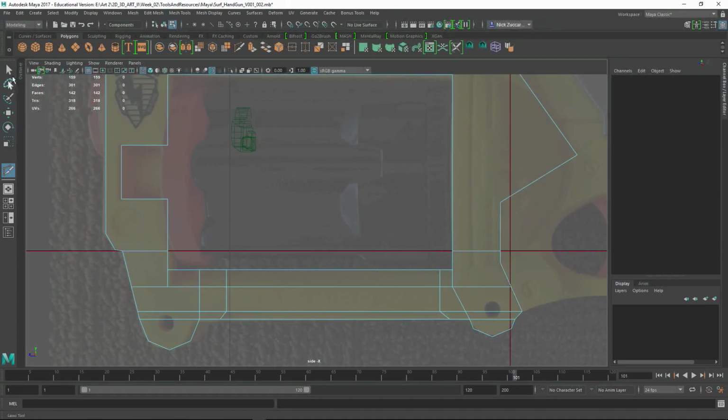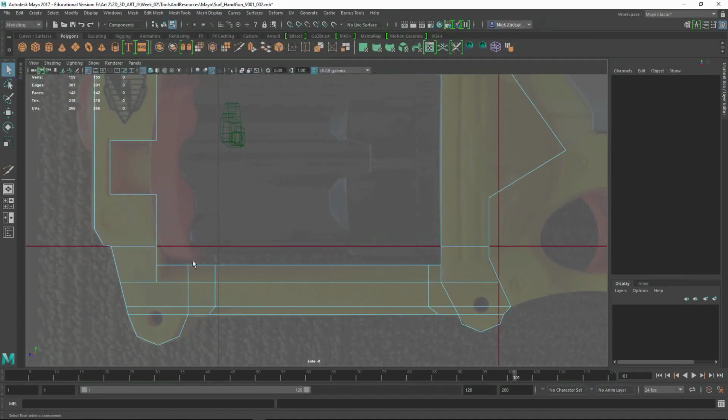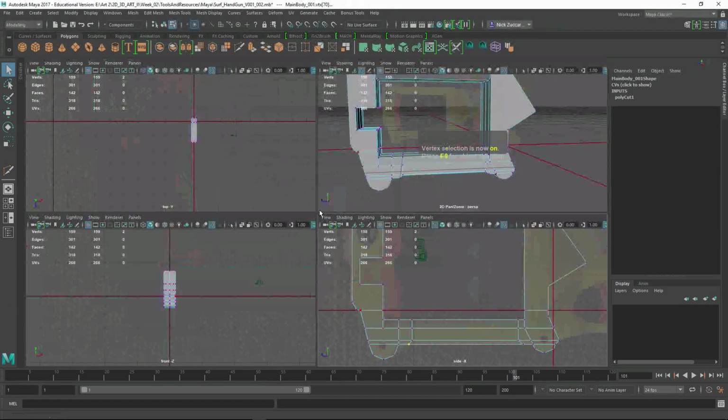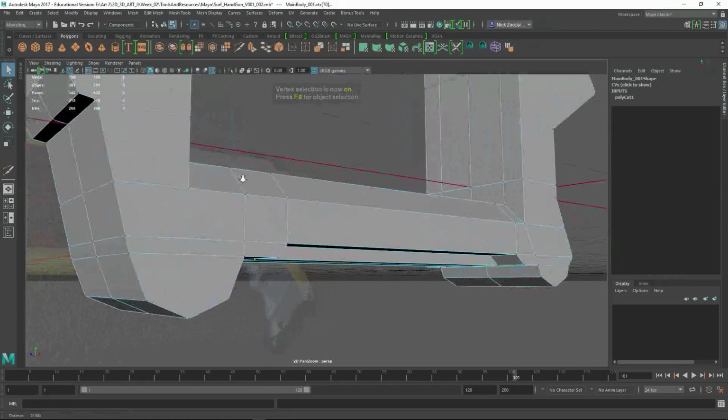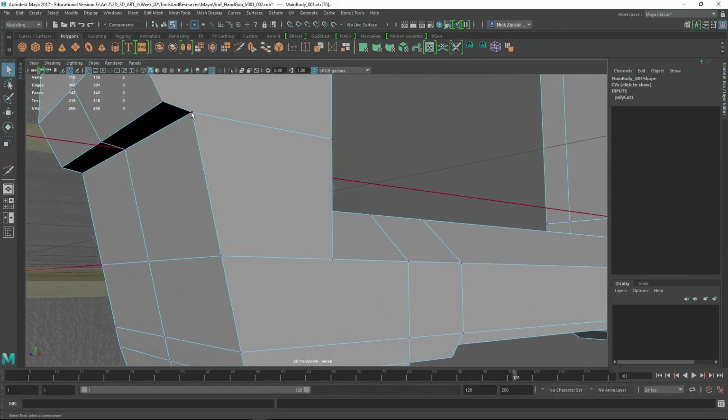Now I do have to be careful, I wasn't super accurate with this thing. So let's get real close here and see. It actually sliced from that point, and I'm just going to move this up and check it. Yep, so it looks like it's really clean, but there's some verts going on there that need to be merged together. Because they're right on top of each other, select these both like that, shift right click and say merge vertices to center, and that'll merge those verts together.